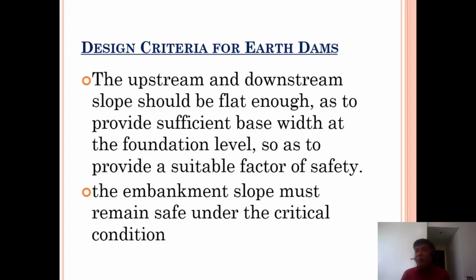But in the software, it is very easy because it is just one click or just a few minutes, you can have different analyses by changing the slopes, changing the base width, changing the crest, changing the freeboard, and so on. Unlike the manual calculation, which will take time. The embankment slope must remain safe under critical condition.